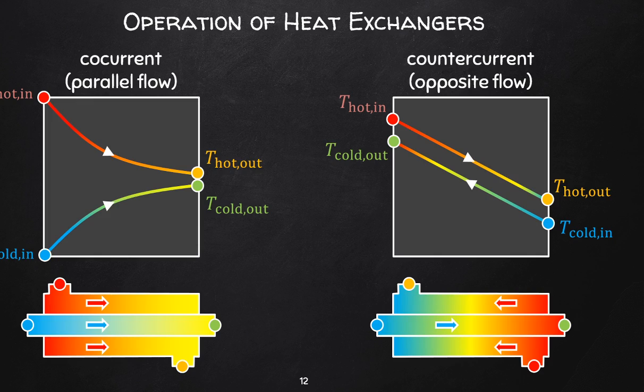So that's really good, anywhere up to 10 degrees. 5 degrees is really, really pushing it. If you go any more, then I think your heat exchange design is probably very wasteful. It's going to be massive.